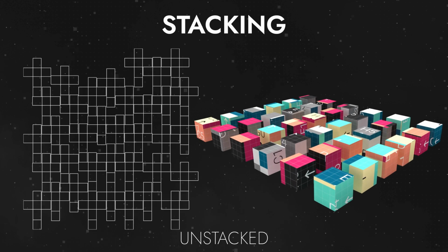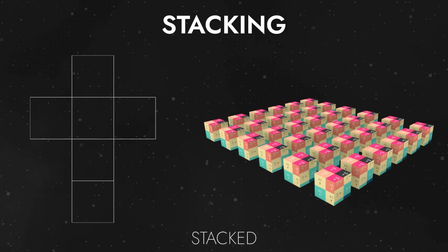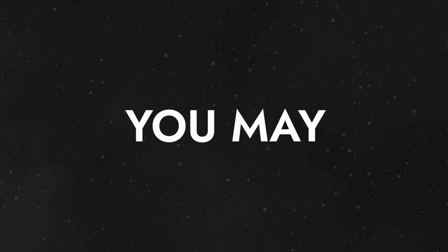And the final one, stacking. If you have repeating elements in your model, you can stack them on top of each other in a UV map. They will all have identical texture, but you can use more texture space for other parts of a UV map.